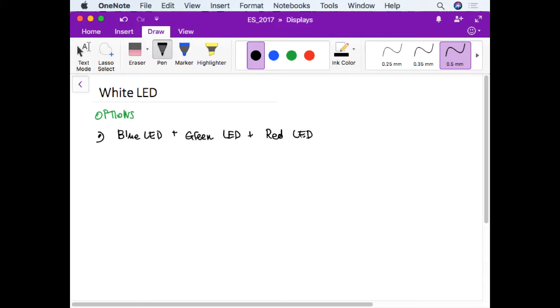This is not general. Now, of course, this is an option, but it is not very commonly used because it has some problem with aging. The problem is that you tune the light in order to have a good white, and then after some time, for example, one of the 3 LEDs has a reduced intensity because of aging, and therefore your white turns greenish or bluish or something. It is not a true white anymore, because for LEDs there is this process of aging, and the intensity of the LED changes with time. Since you have different LEDs, they can age differently.